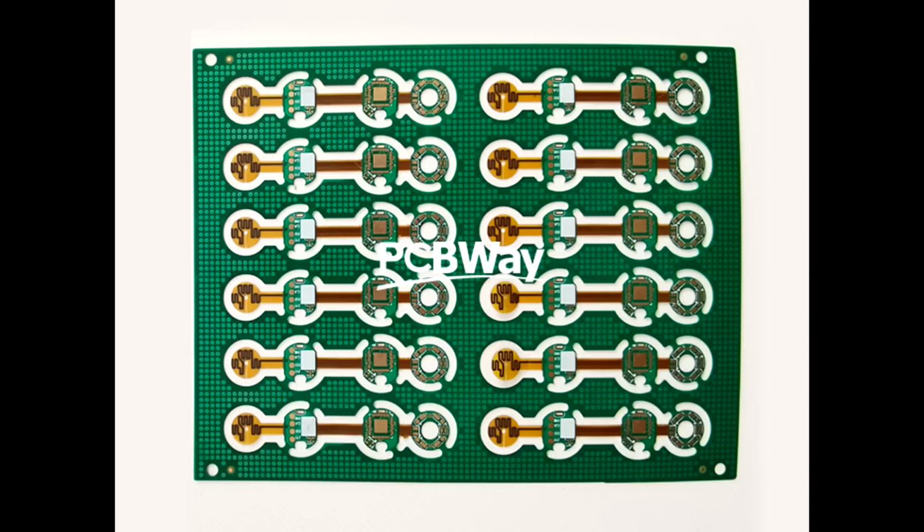I was searching for inspiration when I came across PCBWay's rigid flex PCBs. This means the PCB is partially FR4 fiberglass, that is a rigid PCB, standard PCB material, and partially it is flex, so this is usually polyimide based, a high temperature polymer with copper deposited on it for the traces. This is a pretty nice solution because the flex can stick out of the PCB and it can be very easy to solder. It can be a lot thinner than the rest of the PCB. So then I can treat those pins more like the standard legs of a TQFP package.